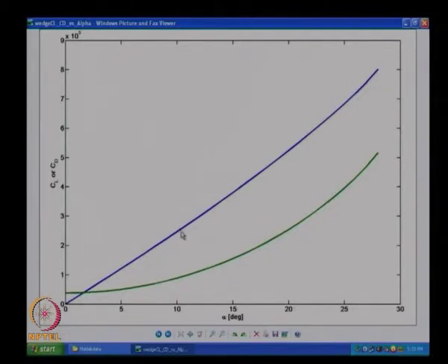The top surface shock will just jump, and the numbers are crazily high here, CD or CL. I think there is probably some mistake here. I think I didn't divide by the correct dynamic pressure, with wrong units. The angle, this number is too high for this to be. It cannot produce more than the dynamic pressure kind of lift and drag. So I think there is some mistake. Probably it is absolute values of lift and drag and not CL and CD. I made a mistake there. It is for Mach 2, 1 atmospheric pressure, 300 Kelvin flow. That is what I have.